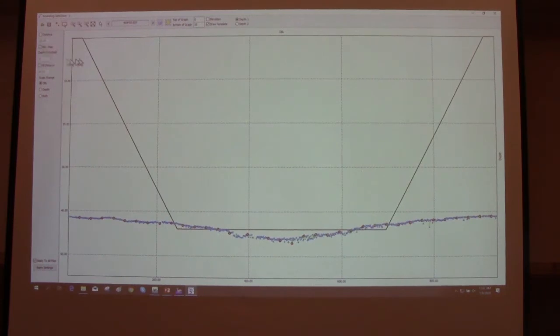Okay, the min-max, like I said, is the depth threshold. So let's put a 1 in here, click on Apply, and you'll see it's just a relatively flat bottom here. But you'll see it looks like we've got a couple spikes in here too, and it's highlighting those inflection points. So I can again maybe ignore one of those. But in addition to the min-max, I could click on the fill distance and do that in addition to the 25-foot range that I had before. So click on that. I got my inflection points over here. And again, I could use this tool to ignore a couple of them if I want to save those to the file.